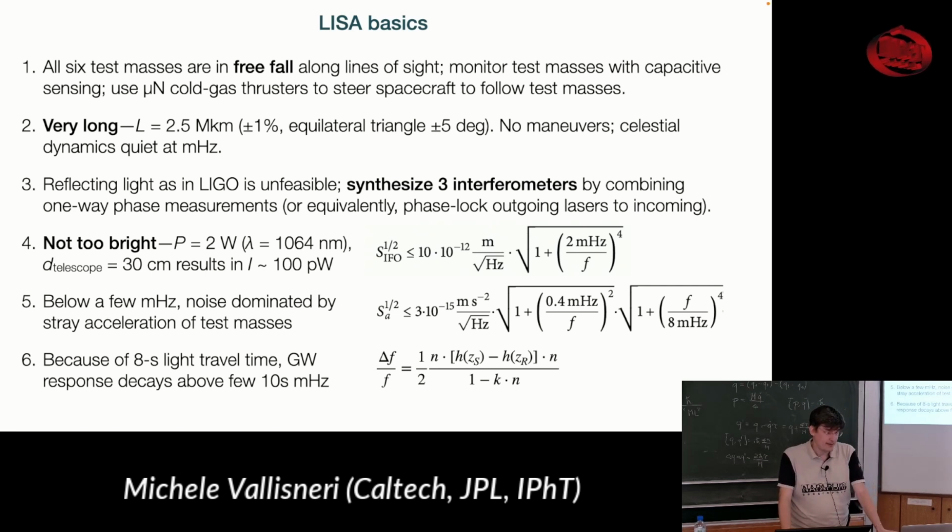to follow it. A cold gas thruster is, how to describe it? It's the simplest thruster you can think of. It uses just Newton's third law. It has gas in it under pressure, and a little valve. You open the valve, you have gas going out. The momentum of the gas that leaves is matched by momentum in the spacecraft. So you're pushing. You're not burning anything. You don't have charge. It's purely a release of neutral gas.